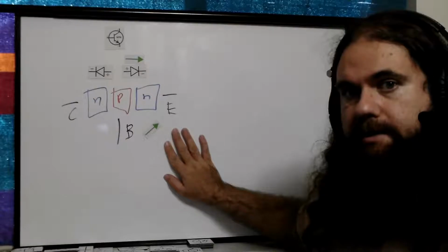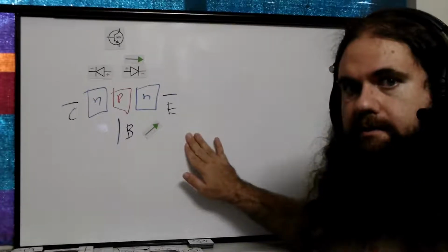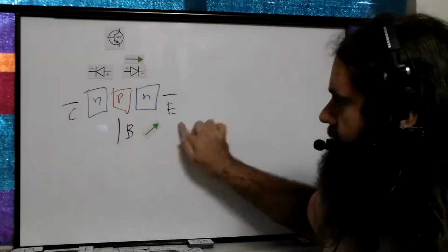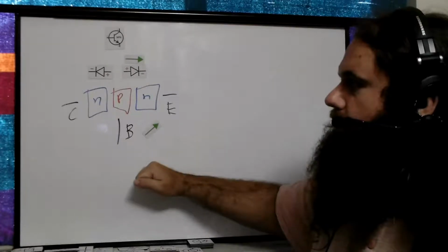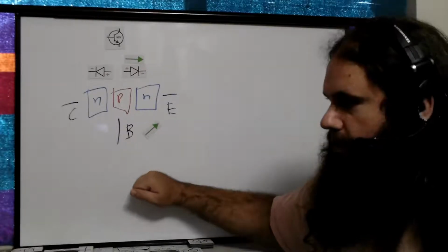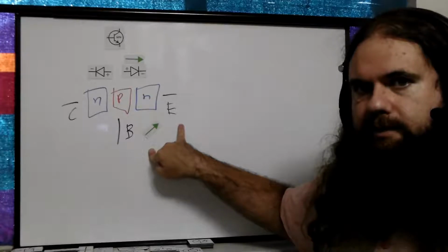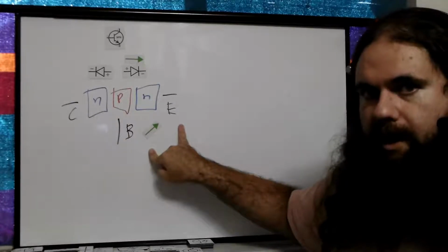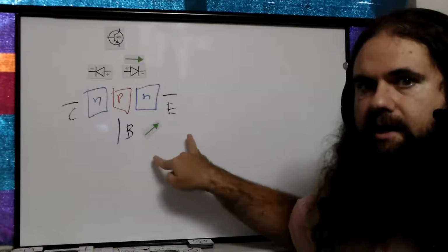Then the current through the base to emitter junction, not the voltage, the current. The voltage only matters for the biasing. Transistors, BJTs, are current controlled. The only voltage that matters is whether this is forward biased. Beyond that, it does not have an effect.